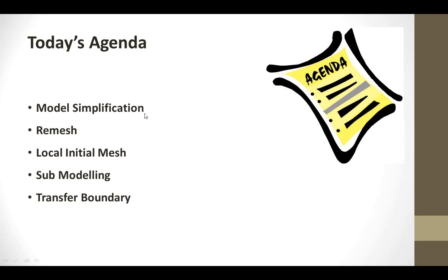For the model simplifications, we will simplify the 3D models. Let's say the fan, we will assume it as a solid and make it assume it as the fans inside our simulations. And inside the model simplification, we also insert all the heat source, all the boundaries, air ins, air outs, all the fans inside it.